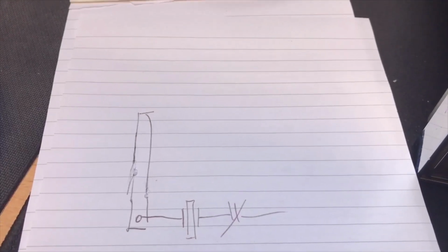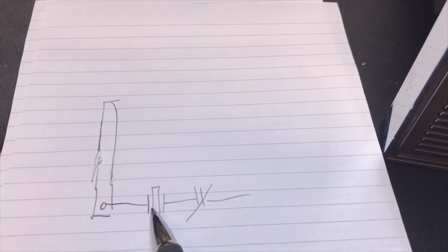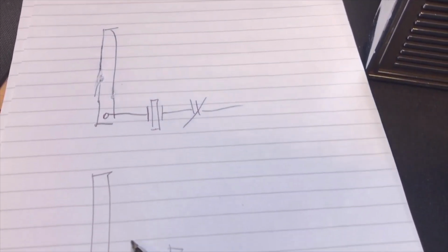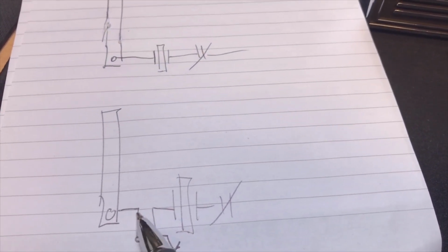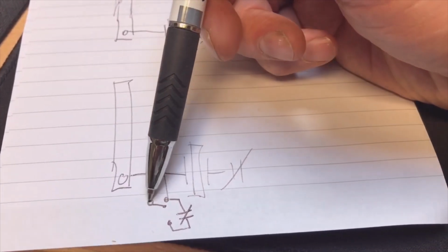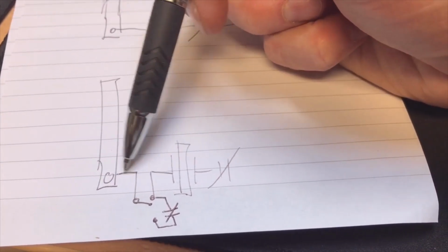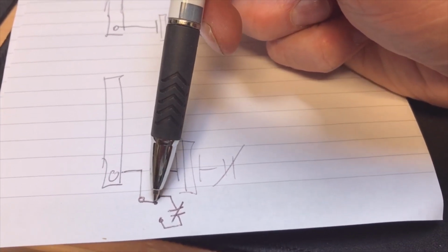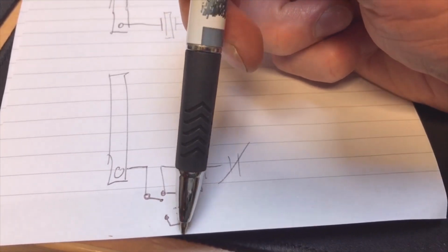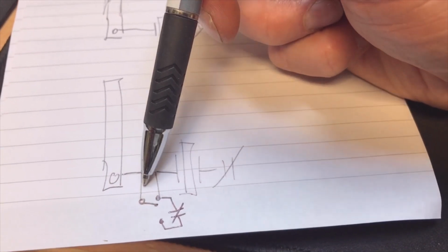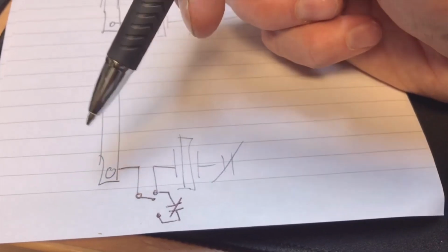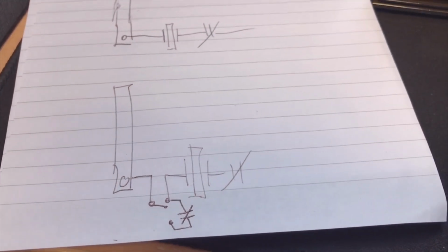So here we have the old situation. The crystal is connected directly to the IC, and here we just have cut this. The rest is all the same. And what we do with the switch, we short circuit, and then it's just like it's directly connected, or we switch to this side, and then this capacitor is in series, and we want it to be adjustable because of course we need to be on the right frequency.